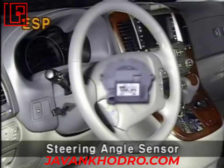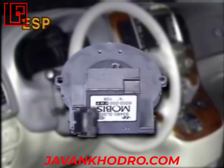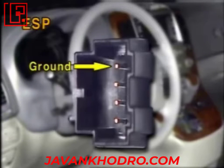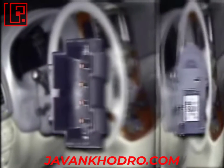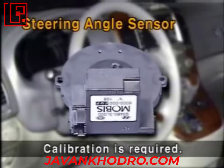The steering angle sensor is installed at the lower part of the steering wheel clock spring. The wire has 4 pins. The first pin is for sensor ground, the second pin is for 12 volts, the third pin is for CAN high, and the fourth pin is for CAN low. The feature of the steering angle sensor is that it is necessary to perform the steering angle calibration.